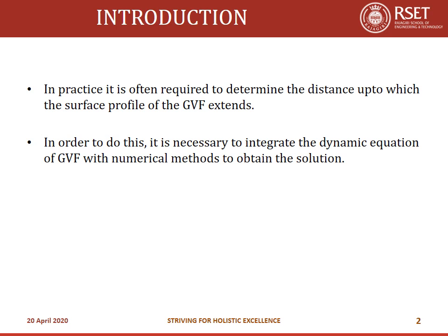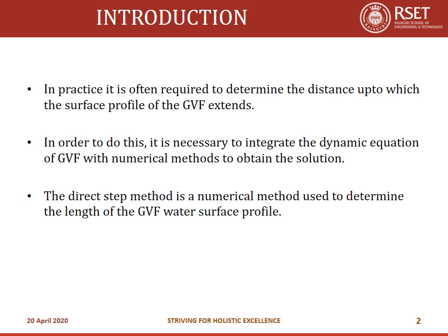So here we are going to convert the differential equation form of gradually varied flow into a numerical equation form to solve for the length of the GVF profile. How it is done, I'll explain. The direct step method is a numerical method that is used to determine the length of the GVF water surface profile.